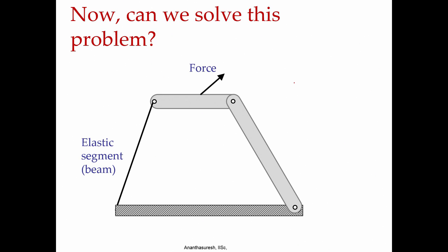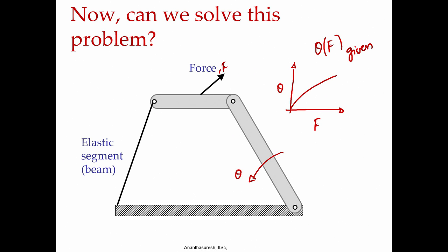If we consider that, then if I have force and I say this was our theta, if somebody gives us this function, that is force F, and says that it should be like this, can I get it? That is, what is given now is theta as a function of F applied here. If that is given, can we design this mechanism? That is exactly what will be equivalent to designing a spring. Here I am showing angle versus force. I could have shown force versus angle, that becomes a spring, a nonlinear spring. That is what compliant mechanisms are in some sense.